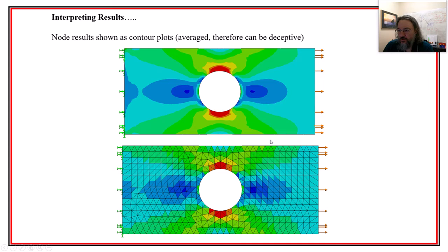And I'll do a couple in SolidWorks Simulation. Do a couple little probes, and you can kind of see, okay, this is the answer at a particular node. But be aware that your mesh density matters. Also, what you're seeing right here is the node generated contour plot, right? But below is what the element plot would be. Now, you don't necessarily want to present this, but looking at it gives you some more information.